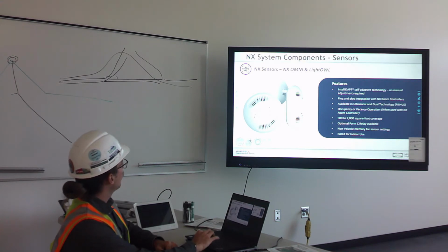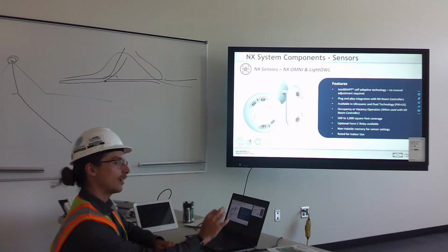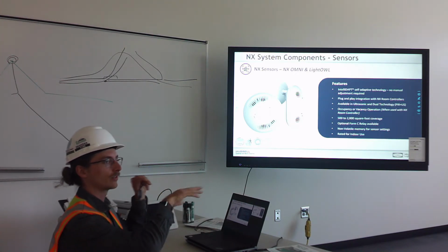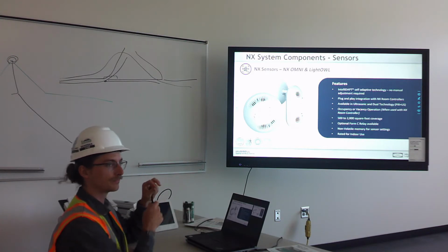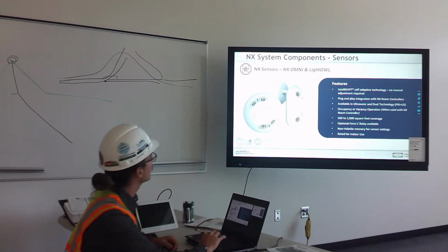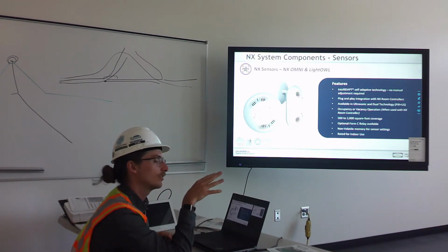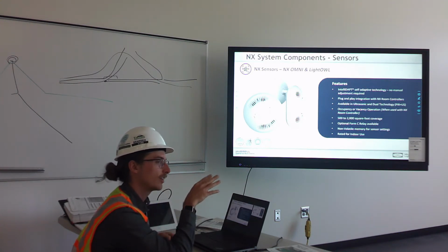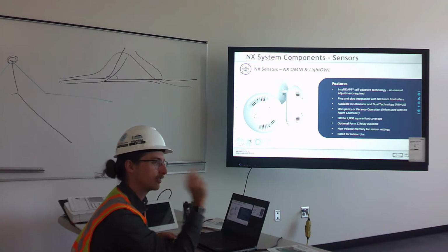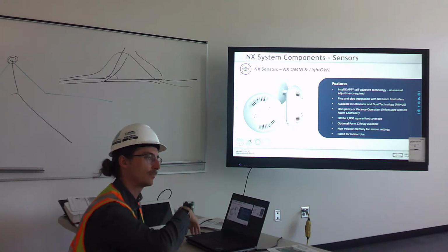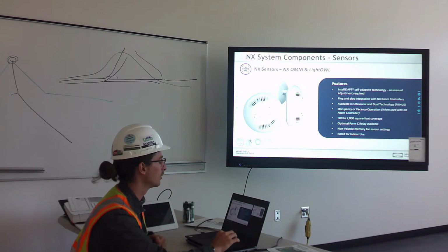So on their default setting, you have to trip both of those sensors for it to actually activate and tell the controller that there's occupancy in the room. How do you change that? Is that through programming? It's on the sensor itself. These sensors aren't digitally communicating to the controller. All that's happening is a signal wire lights up 24 volts when the sensor picks up or thinks the room is active, and then drops out to 0 volts when it thinks the room is unoccupied.